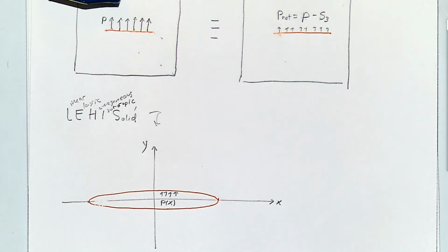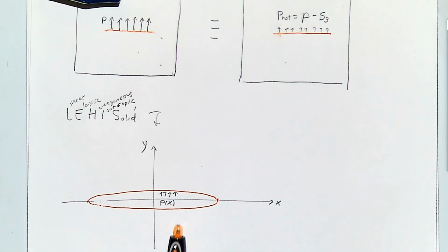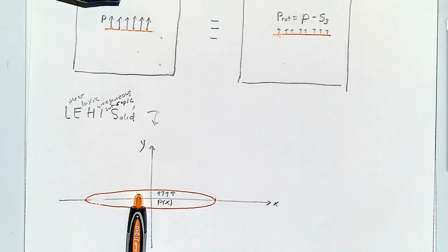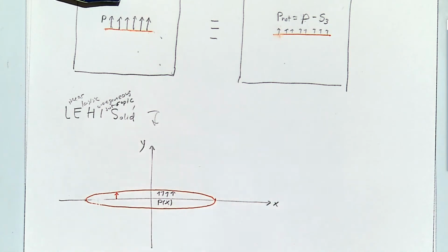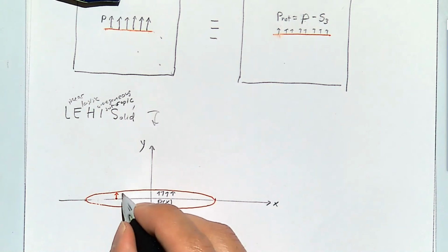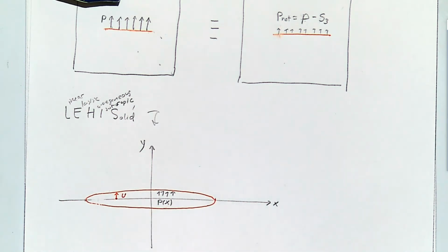Hopefully, you notice too that since this linear crack before was closed, now it's open, it displaced a certain amount from the center to the new position, and that's going to be a displacement in direction y, and in this case it's going to be a function of x. So for example, displacement here is some value, but beyond the tip it is equal to 0.